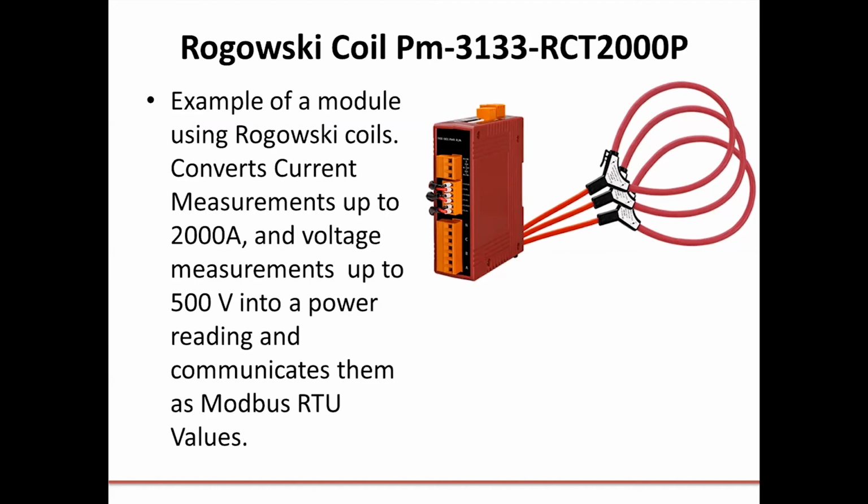These compact and cost-effective power meters use the Rogowski coil rope-style current transformer, which makes installation easy with a large window size of 55 to 185 millimeters, and mechanical flexibility if you're operating in tight spaces. It operates over a wide range of input voltages, 10 to 500 volts AC, which allows for universal compatibility.